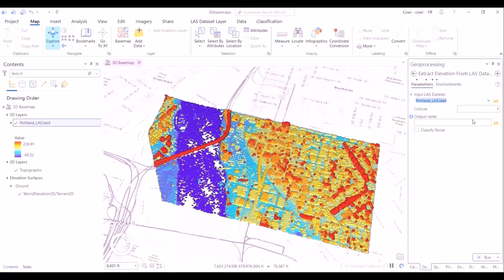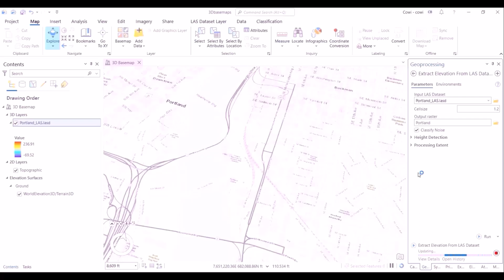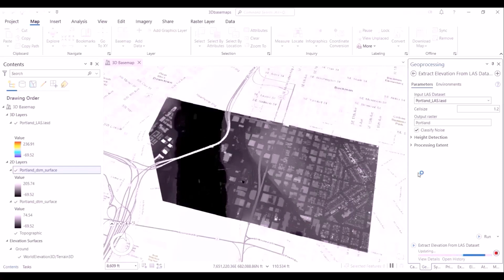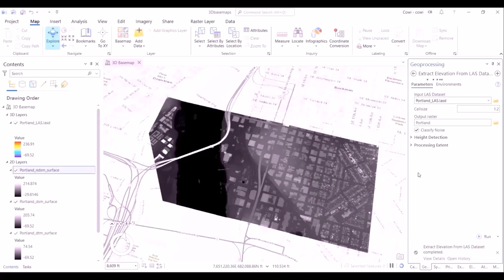This is where we'll do something different from the building footprint exercise. What we'll do is we'll extract the elevation values, but of 3 different types. One is the default digital elevation model, which captures the height of the features on the ground. But beyond that, we will also extract the digital surface model, which captures not only the height of the ground level features, but then also artificial or natural features above the ground level, such as vegetation or buildings or any other features respectively.